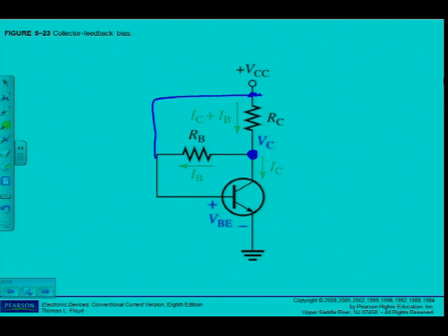So what is going to happen in this case? Okay, what was the problem? Changes in beta DC, né? The biasing circuits are too dependent on beta DC. So beta changes with temperature and with changes in collector current. So that is a problem.